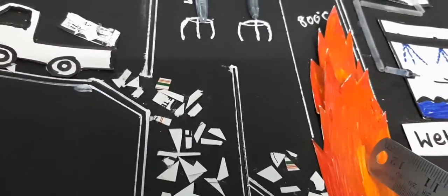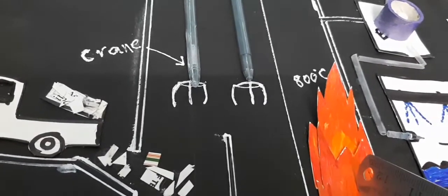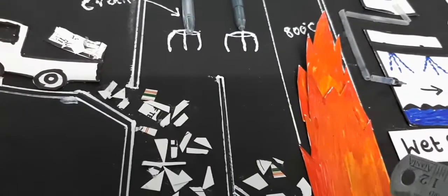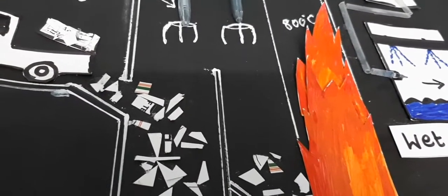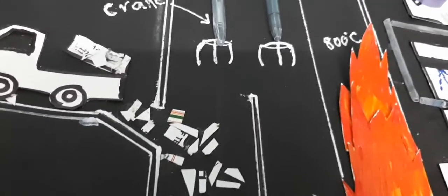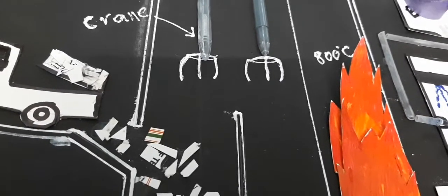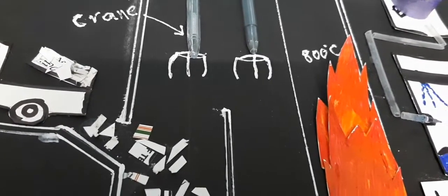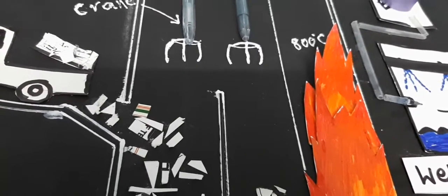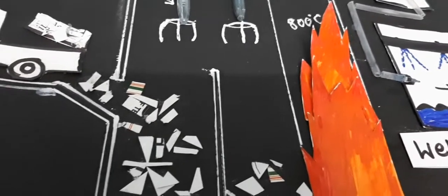The temperature achieved in the furnace is a result of heat released by the oxidation process and must be maintained high enough to ensure complete combustion, but it should not be so high as to damage the equipment or release excessive nitrogen oxides.